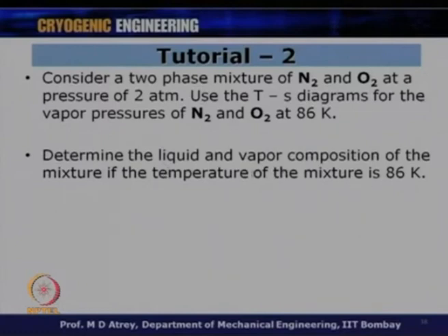All right. Now, I can't use the table. This is what is mentioned over here, that I should use the vapor pressures of nitrogen and oxygen at 86 Kelvin, and this is basically in order to calculate the values of Kn2 and KO2 theoretically. As you remember, theoretically we do not consider real gas values, where no intermolecular forces are considered, and that is where this is coming from, that I would like to take the vapor pressure values of nitrogen and oxygen at 86 Kelvin.